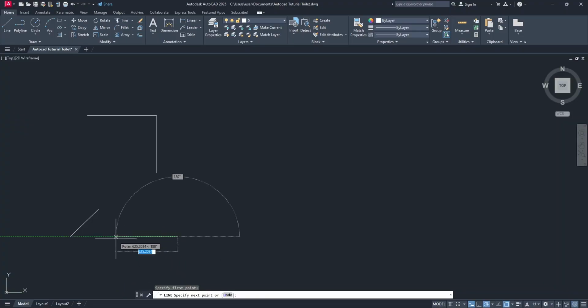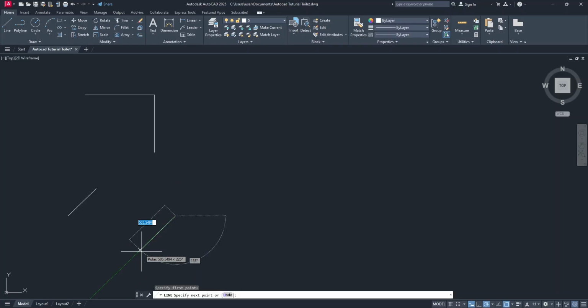Once your angle hits 180, it reverts back to 0. It doesn't continue to 360. That's why here it will show you 135, but on this one it will show you 225. Bring it here, which we know is 270, but in AutoCAD it's 90. Here we really know it's 315, and in AutoCAD it's 45.